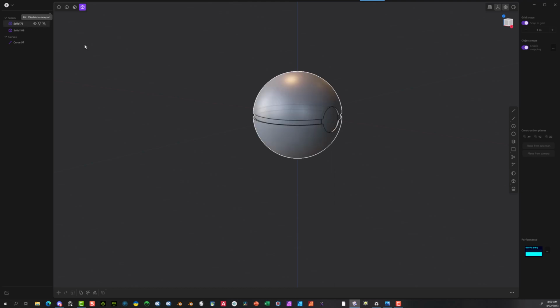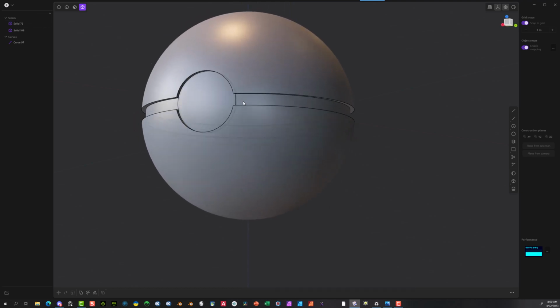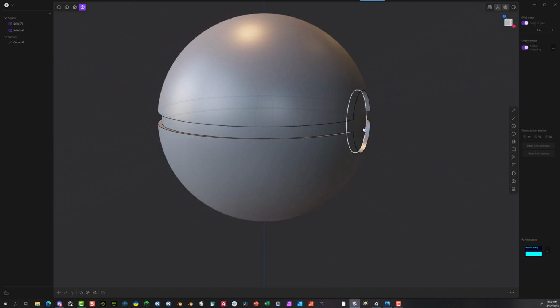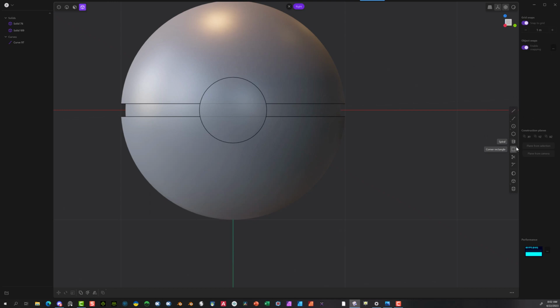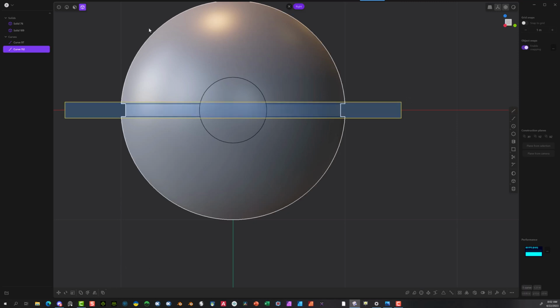So now if I hide this, you can have exactly a perfect rounded section there. Let's say this looks too small and you want to bring this a little higher. You can go back into the X-axis and select this tool here again. Originally we had this at, I think it was, take the grid snaps off again, 0.25, or 225. Let's say you want to make this a little bit wider. Let's say 3. I'm going to select this out. Let's hit 3. So you can always go back and change the dimensions.